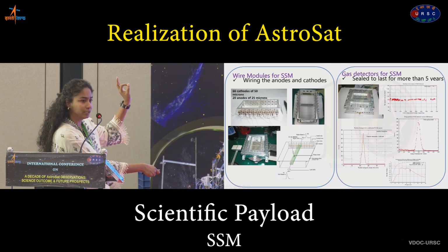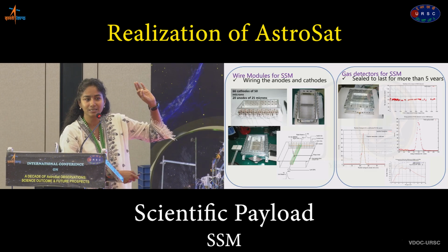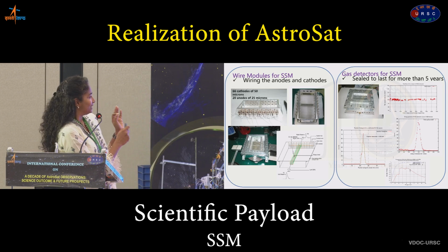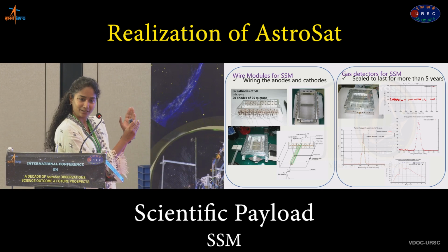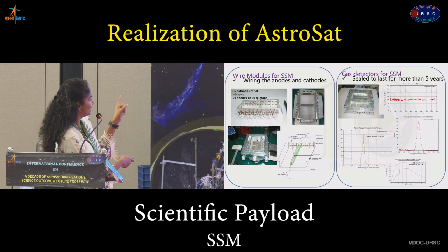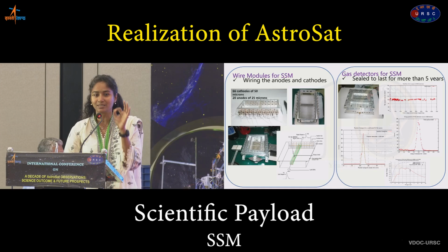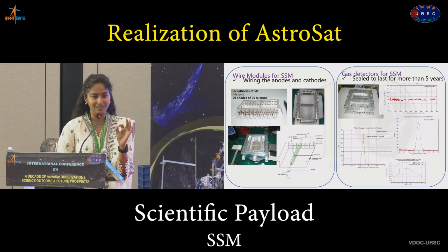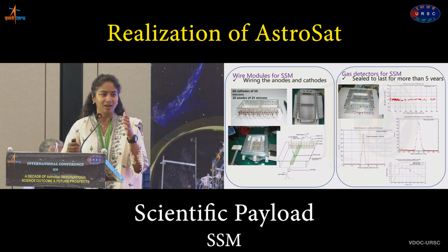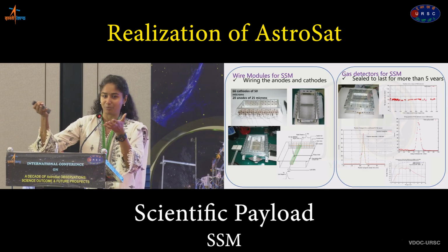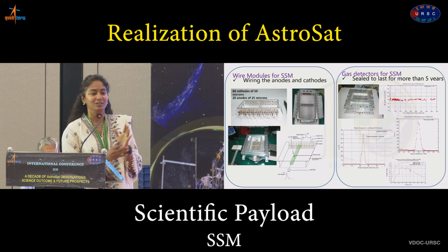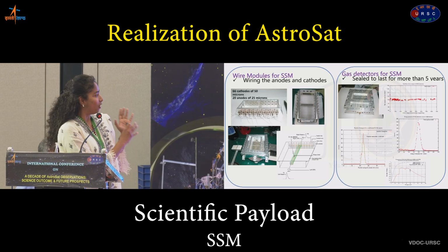So there are totally 20 cells. Each cell is an individual independent proportional counter. So it's like handling 20 detectors in a module. And so 66 plus 20 anode wires, which is 86 microns wires, diligently wired. The wiring mechanism was done in-house. Mr. Chandrababu here must be watching this. He was instrumental to do this brilliant effort of making this happen.